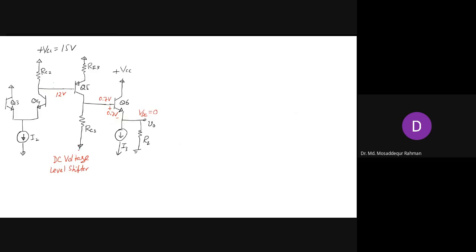So this is going to the other supply voltage. You see how the op-amp is connected. You have plus VCC, minus VCC, right? Plus supply voltage, negative supply voltage. So the voltage at this end, if you call it minus VEE, should be minus 15, something like plus 15, minus 15. So say minus 15 volt here, right? Then there should be some current flowing here.